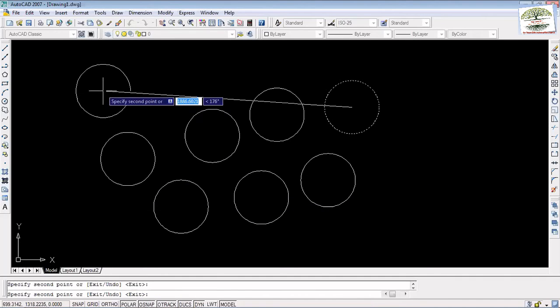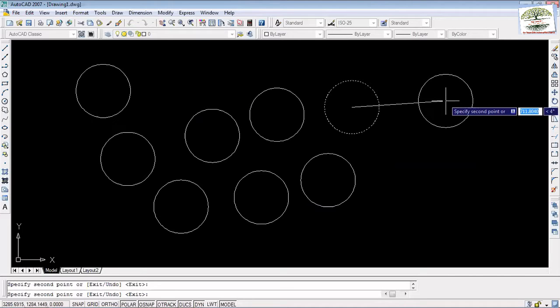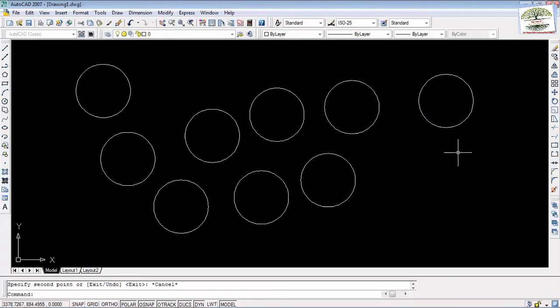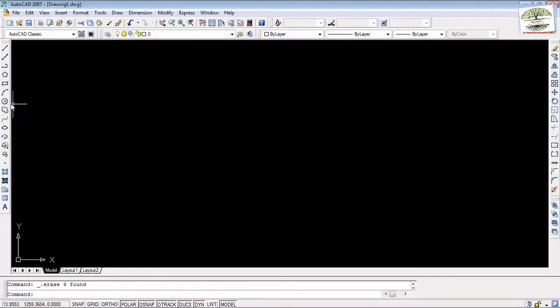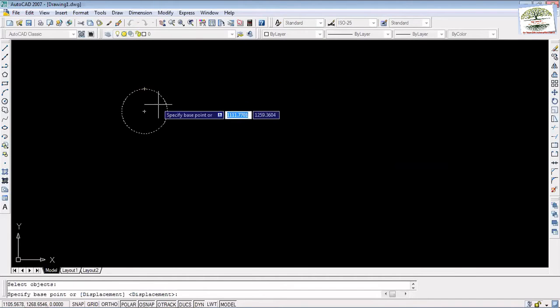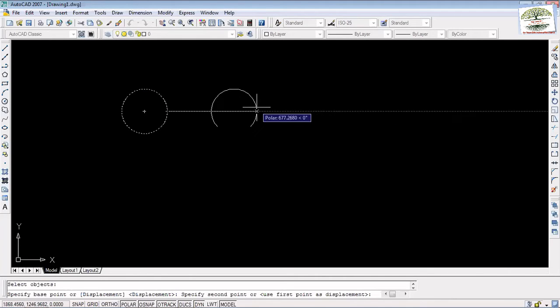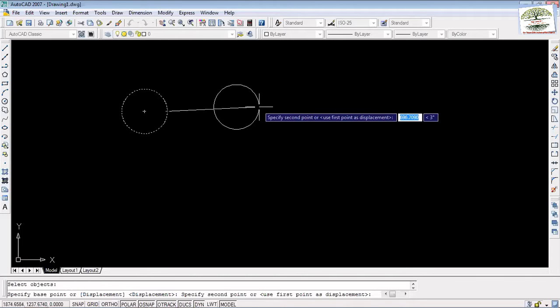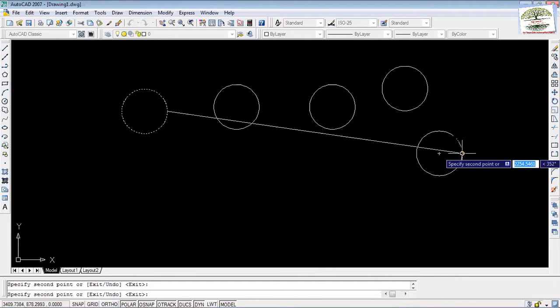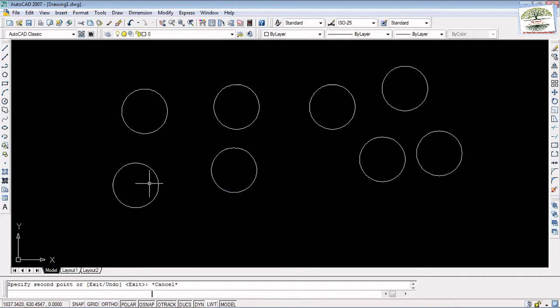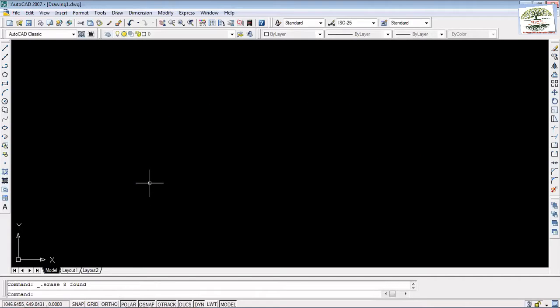Now the plus sign cursor is in the middle of the circle, whereas initially, when I selected the circumference of the circle, the plus sign was residing on the circumference. Just before this, it was at the center of the circle. This is what I was talking about: selecting the reference point along which we'll copy the object.